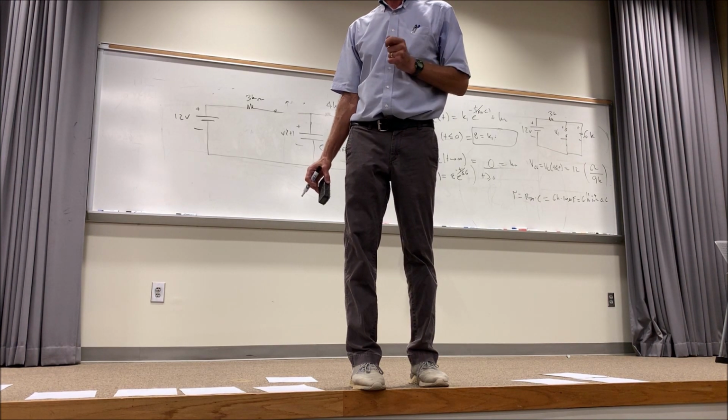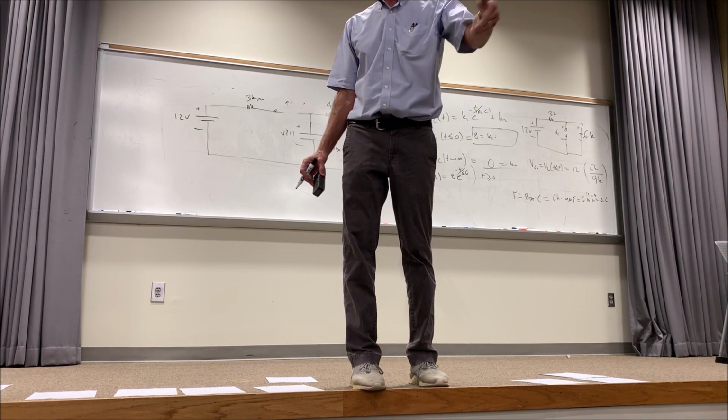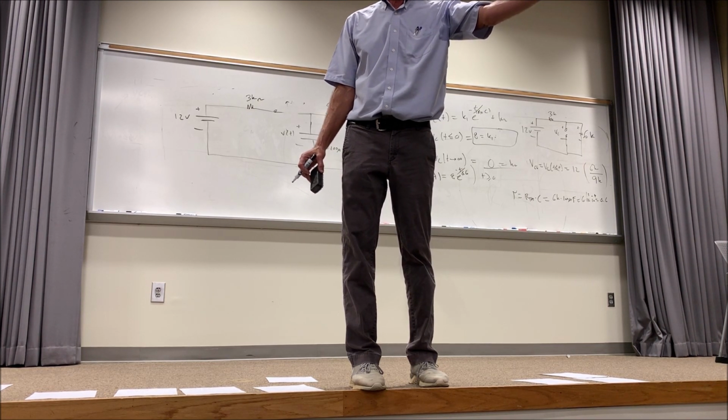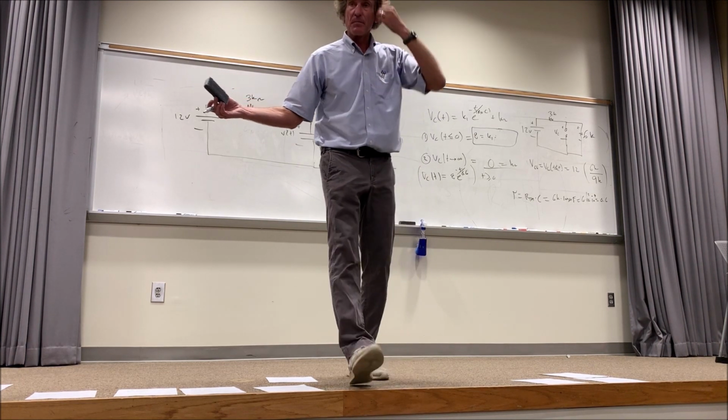Yes. So we do R Thevenin based on the system after 0? After the switch transitions. If it transitions at 1 second, look at it at 2. Think of t equals infinity. Find that value. All right. You can't go wrong there.